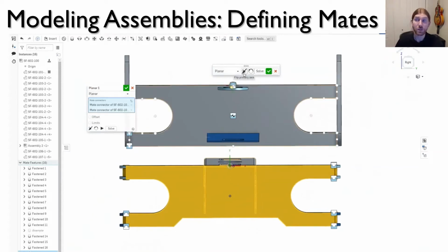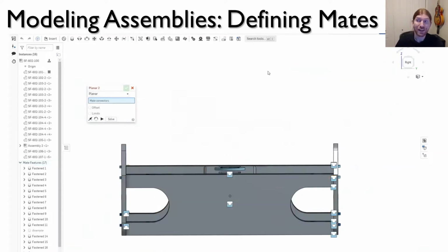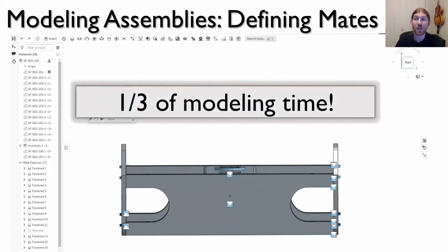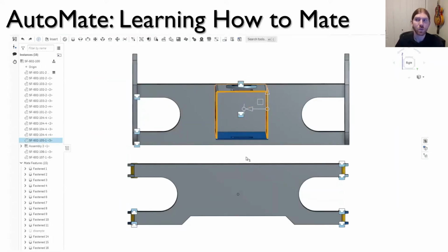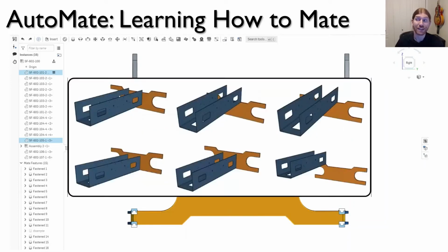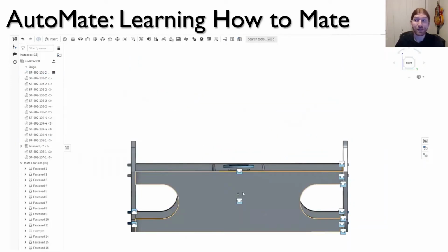In CAD, creating an assembly from parts is a time-consuming manual process of selecting, placing, and mating parts, which requires both careful positioning of the parts in reference to one another, as well as specification of how these parts can move relative to one another. In practice, users spend roughly 1/3 of their time in modern CAD tools in assembly work. In this work, we develop novel machine learning techniques for predicting how to mate parts. In our tool, the user selects the parts they want to mate, and our system suggests mate locations and articulation types.